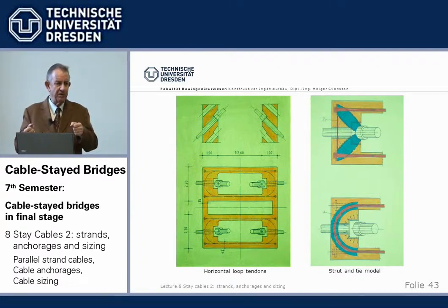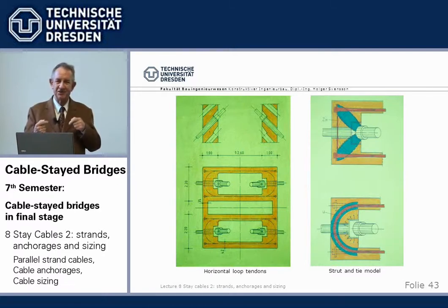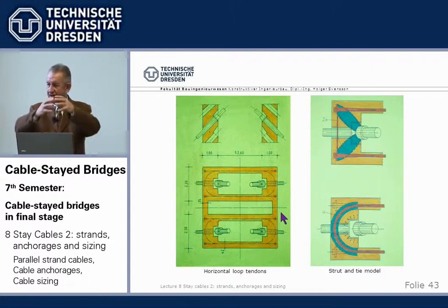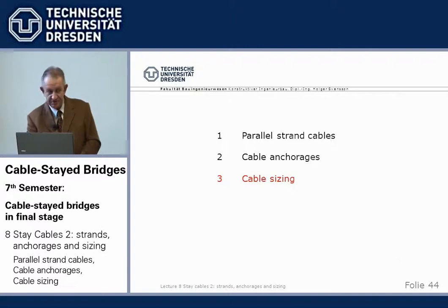Well, that's all very beautiful, and I've done it twice for Helgeland and Baytown Bridge, and it's very nice. However, contractors say, well, that's all very tedious, and it is short tendons. I mean, this was 12 meters. Okay, we made it double, but it's short tendons and so on. Although it's a very good system, it's not much used today. It's used the steel part, cast in, and don't fiddle around with the tendons. That's how the practical use sometimes overcomes the good theoretical solution.